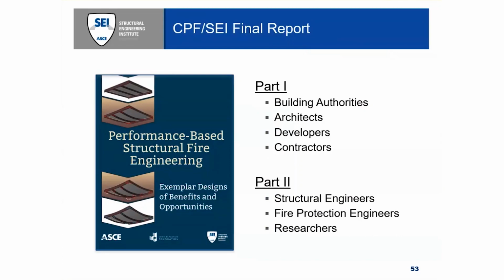Okay, what we show here are essentially force diagrams under different points in the fire. We really want structural engineers to be able to relate to this technology. So fire is not some exotic thing that is beyond your expertise per se. You may need assistance from a fire consultant, but you already design structures in a lot of cases for thermal expansion, but now we're just talking about a lot more thermal expansion and contraction.